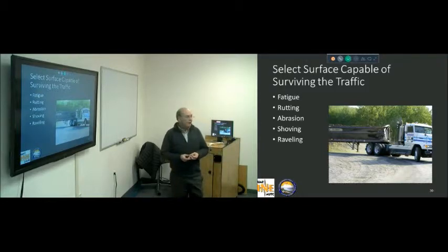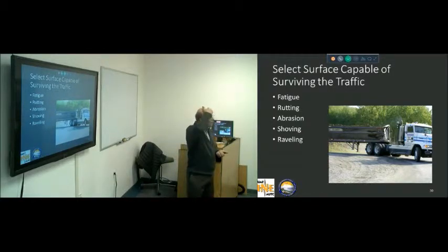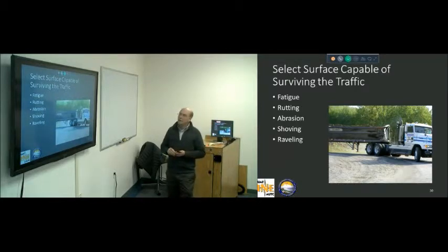Shoving is a property of the asphalt itself. That's when the asphalt, as people are moving out, gets pushed off to the side. It's akin to rutting, but not quite the same. You can see some extreme examples in intersections where it wasn't designed for people stopping and pushing the asphalt, and you'll see a sort of rut, and then a hump right where people are stopping. That's a form of shoving.